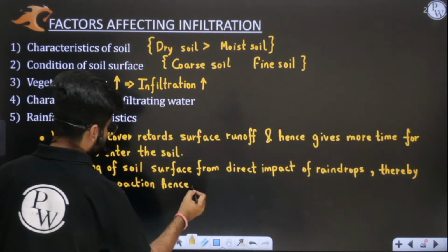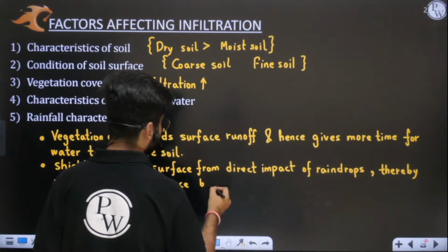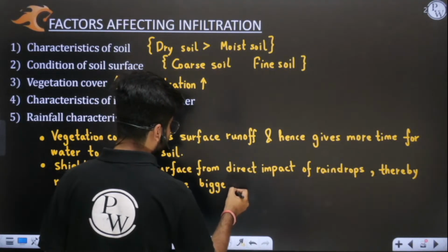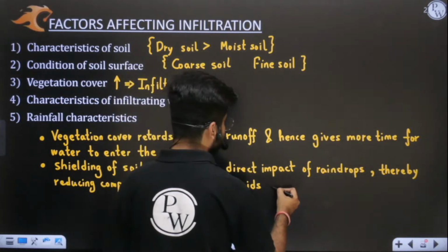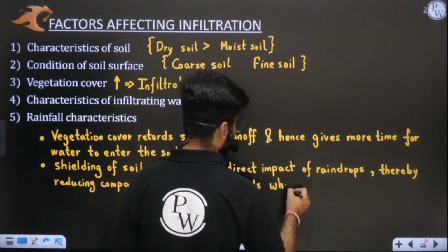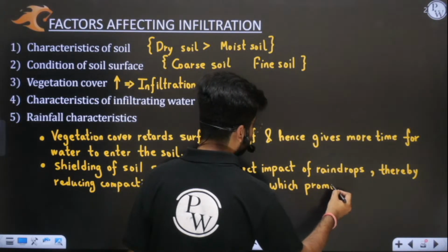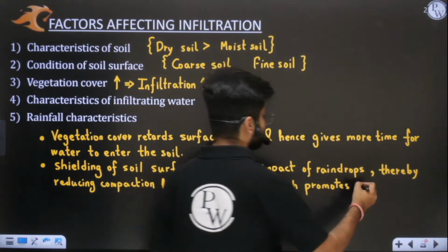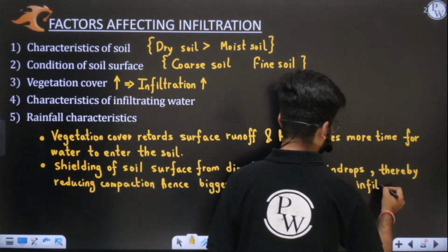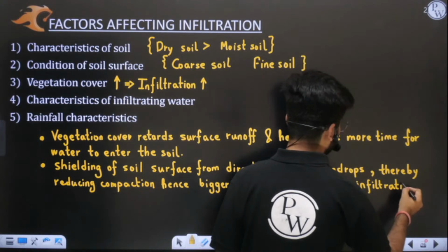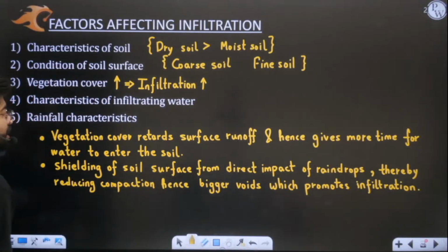Hence bigger voids are there, which in turn promotes infiltration. So these are the 2 important points with the help of which you can understand the effect of vegetation cover on infiltration. I hope these 2 points are very clear to you. This I have explained to you and now I have written here.